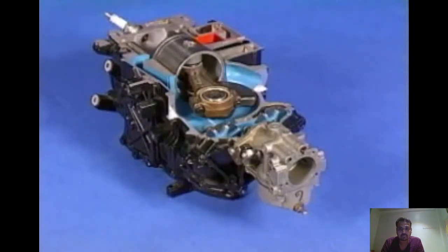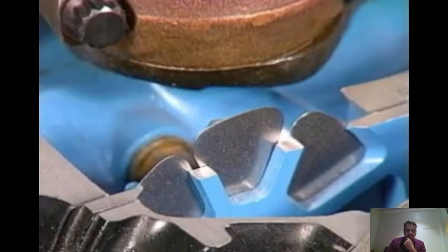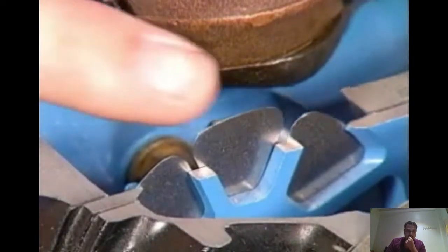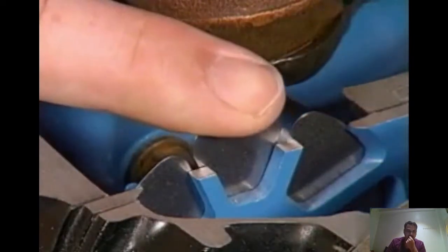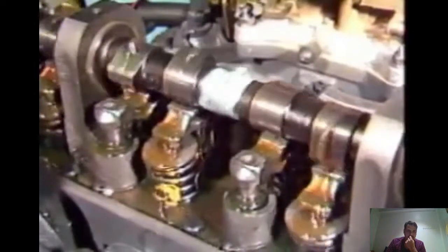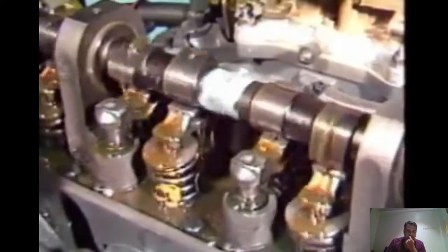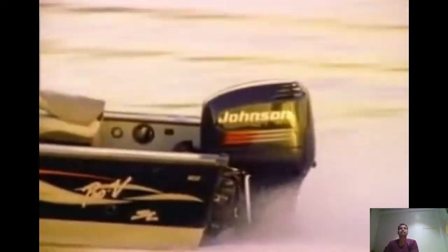Two-stroke engines are much simpler than four-strokes. Reed valves are small and lightweight. They don't need any mechanical linkage to make them open and close, since the pressure inside the crankcase does that quite well. On four-stroke engines, the valves are held closed by springs. A camshaft driven by the crankshaft opens the valves at the correct time. All of these parts add weight and take up space, so the two-stroke enjoys a significant advantage when you need a lot of power in a small, lightweight package.